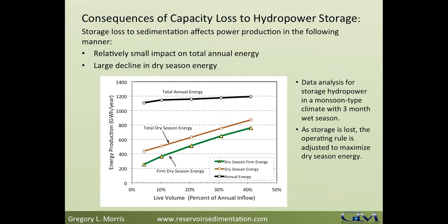When you build the dam, you cut off this coarse sediment supply, you end up with degradation of your bed downstream, you end up with coarsening of the bed downstream, you end up with a more simplified channel, a lot of environmental impacts associated with dam construction.